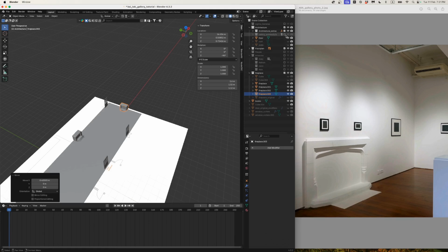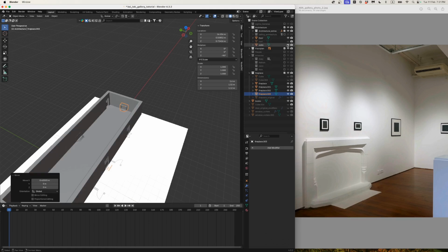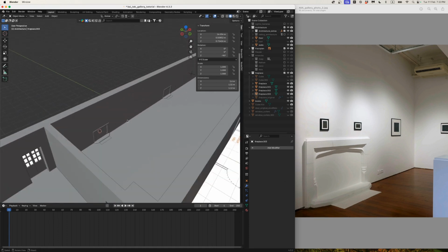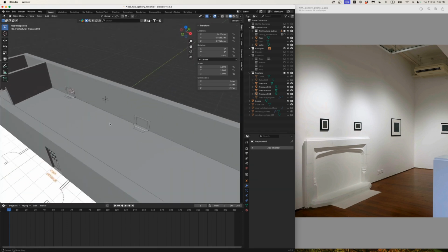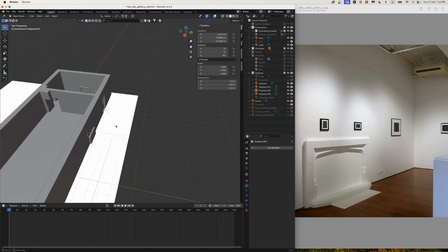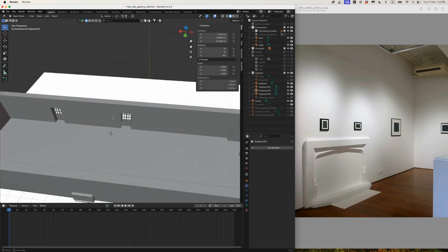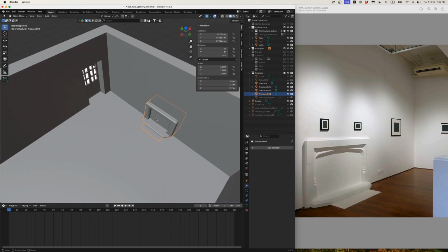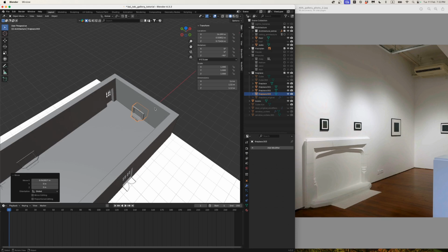And now let's just have a quick look and bring back our walls and just see if we're sort of in the right territory here. I think we are, because they're sort of sitting into the walls like that. This one should go a bit more, probably something like there. And then the last thing we can do, depending on what we need to do in our rendering, especially if we're doing any animation, you can always just Boolean these onto the walls just to avoid any overlapping polygons.